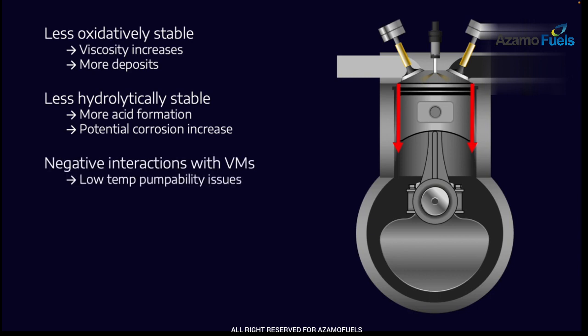There is also some evidence that there is a negative interaction that happens with certain types of viscosity modifiers, and you can run into some low temperature pumpability issues. This seems to differ depending on the type of viscosity modifier, but without much information about the formulations of some of the diesel engine oils, it's very difficult to predict when this will happen.